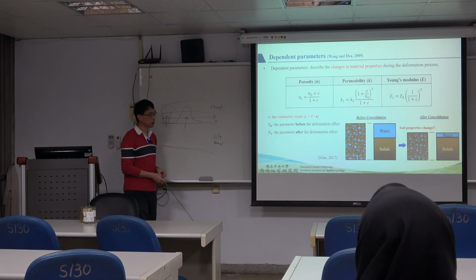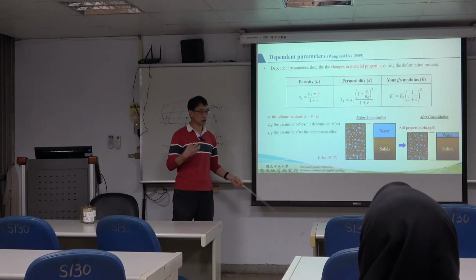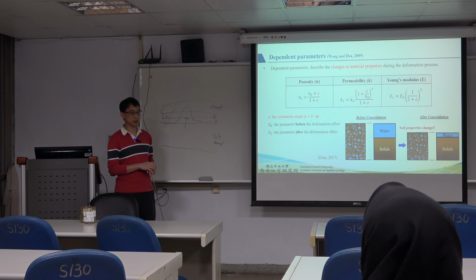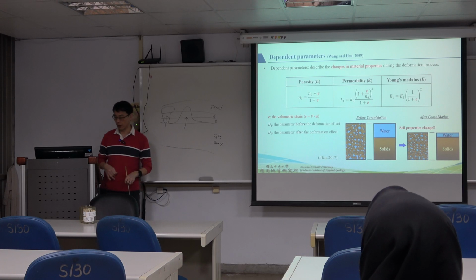And dependent parameter means that we try to assess when the compression occurred. The void ratio will further influence your porosity, and further influence your permeability and Young's modulus, or your rigidity. So it becomes iterative, not only constant values.